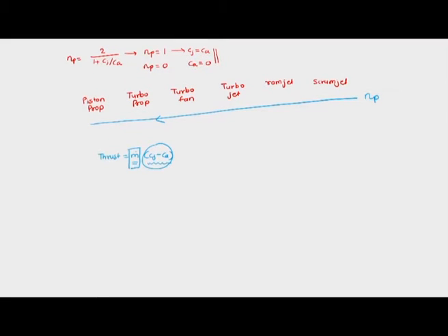But there is one more aspect to look into, that they need a large amount of mass. So they cannot be traveling at larger altitudes, they will travel at lower altitudes. But the other engines which rely upon larger velocity can handle a lesser amount of mass, so they can go to higher altitudes. So this is how propulsive efficiency is going to define how the design of the engine is going to be.